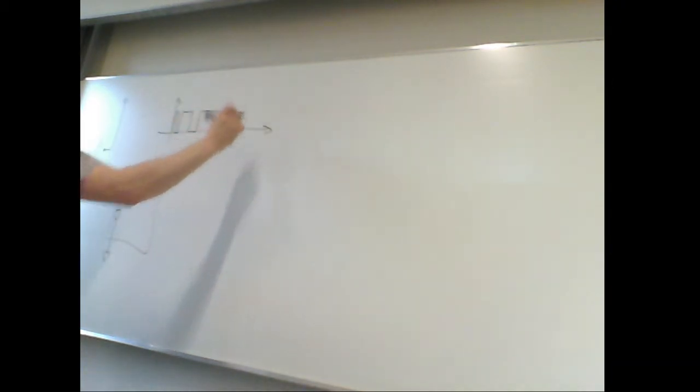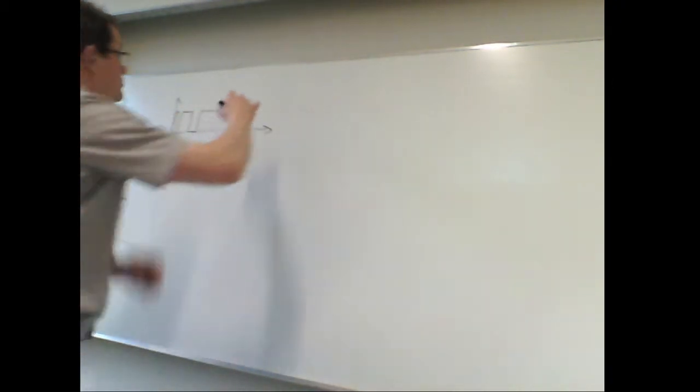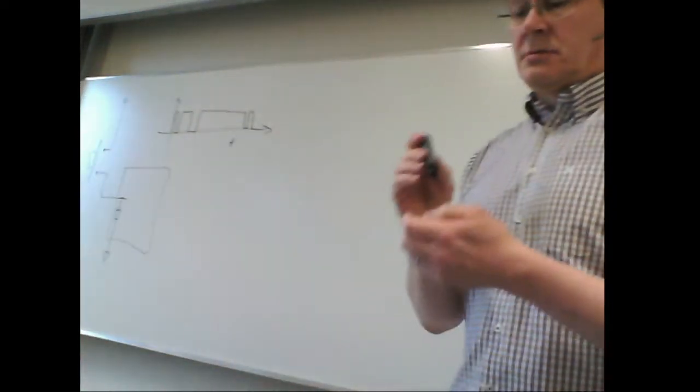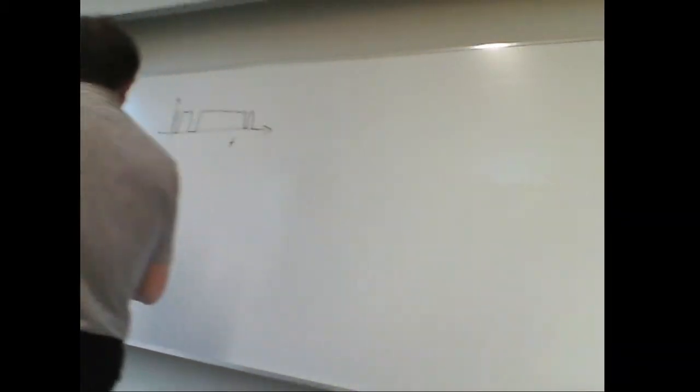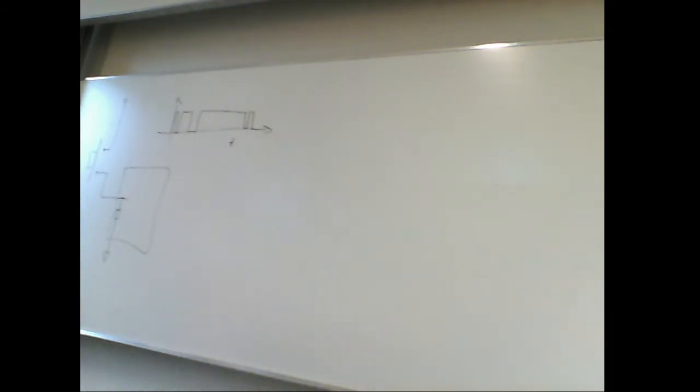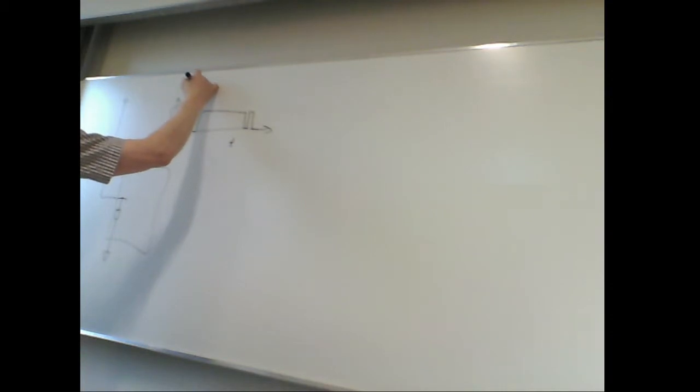And finally it's stuck there. The same thing when you release it. It doesn't release immediately, but this kind of thing usually also happens on the other edge. So you can get rid of these when you have an interrupt happening, for example, on a rising edge interrupt.